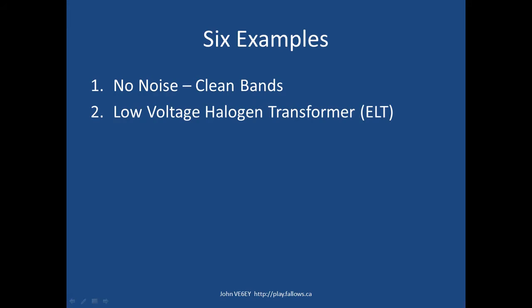So there's an example of using a noise canceller to get rid of birdies. You can use the notch filter, and in fact the Flex radio's got a tracking notch filter that'll get rid of them at the front end. So there's various ways to deal with those.